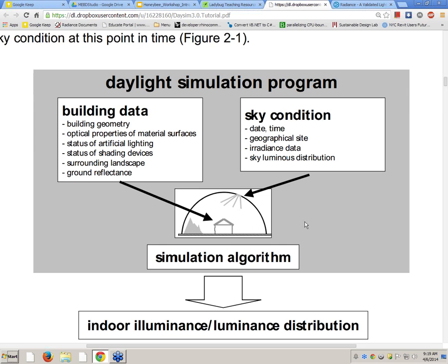So in daylight simulation, that light source is the sky. And then you say run or render or press F5, something, and it starts finding the relationship between this geometry and the sky. Based on how much light you get at each point, you will get a rendering, based on the material and all that stuff, right?